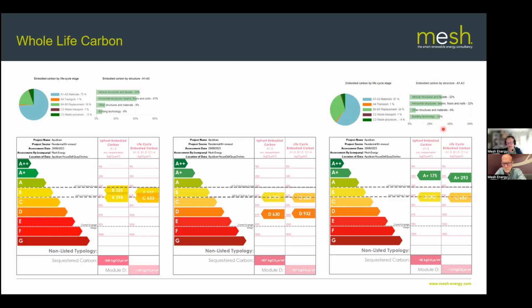But then, because it's a more organic construction, made predominantly of timber frame and wood fiber insulation, that starts to reduce the embodied carbon of the structure, and so it leaves room for designing for resilience, or bringing external masonry elements in, and making the fabric more resilient in the face of climate change.